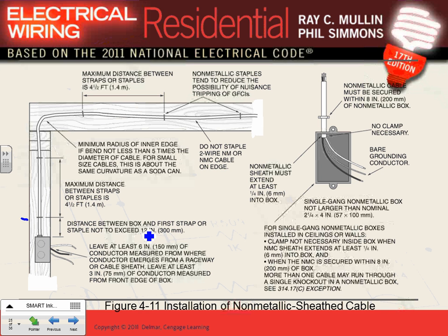When you staple, you always staple 12 inches from every metallic box and 8 inches from non-metallic boxes. That's rule number 1. 12 inches is typical for all cables. When you're using non-metallic boxes, you have to reduce it down to 8 inches.